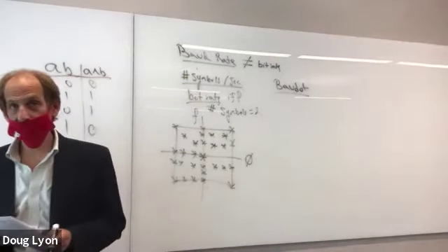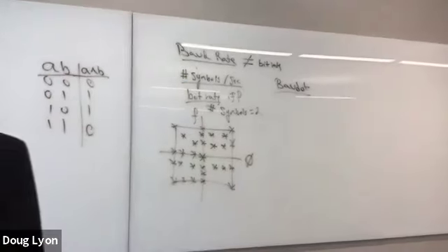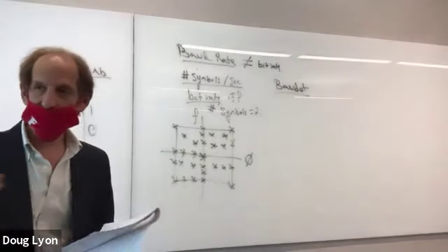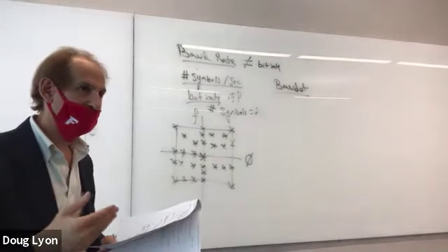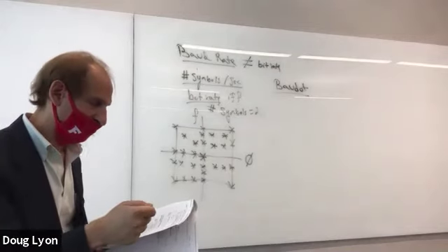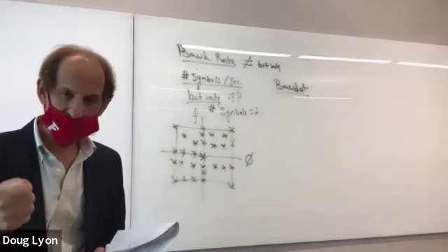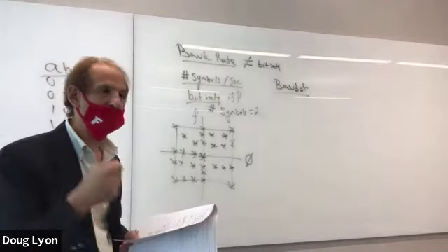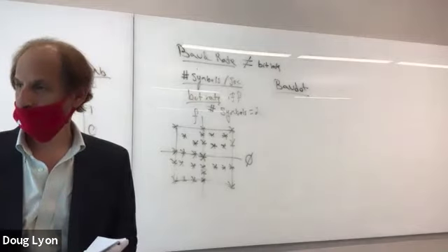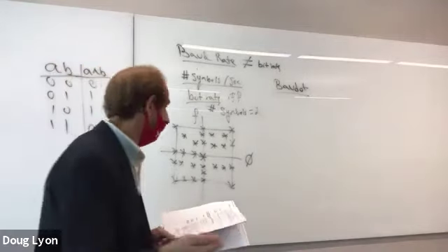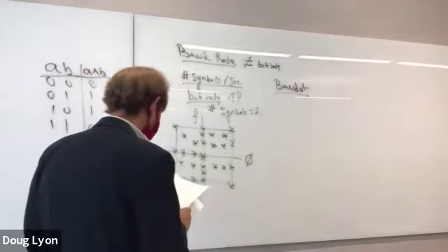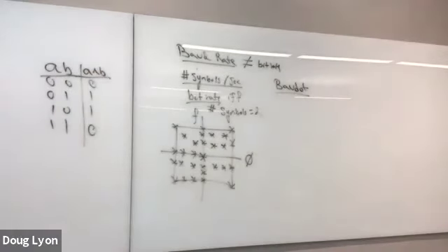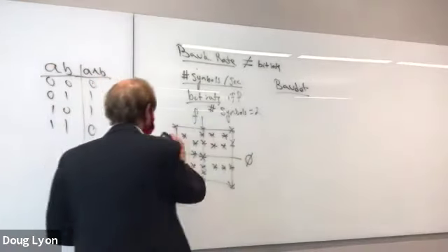Serial communications is very important for microcontrollers because they need a way to talk to the sensors and to talk to other computers. So for example, when you plug the USB interface of your Arduino into the USB port on your computer, it's using a serial communication protocol. In fact, it's simulating a serial port that uses what's known as asynchronous communications.